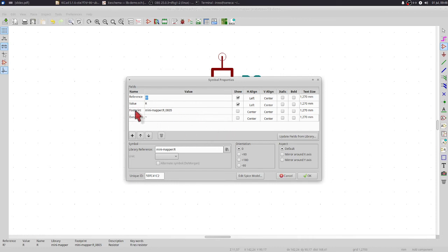That might change a bit for some things like bigger capacitors might need bigger footprints, and I'll have to think about that. But basically, most of the time, I'll use 0805 resistors. Most of the time, I'll pick one footprint for one part and use that all the time. So this thing's got a footprint.